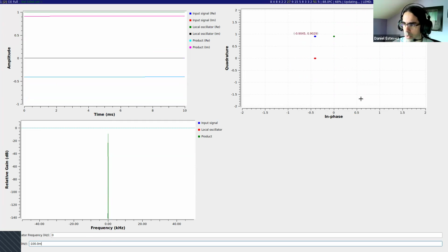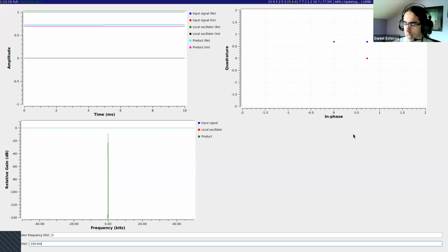So I hope this example really convinces you that positive and negative frequency is something that happens in complex numbers because they are 2D, two dimensions. When we have a real signal, there's just one dimension and we cannot tell the difference between positive and negative frequencies. They are intrinsically the same thing. Any questions about this?